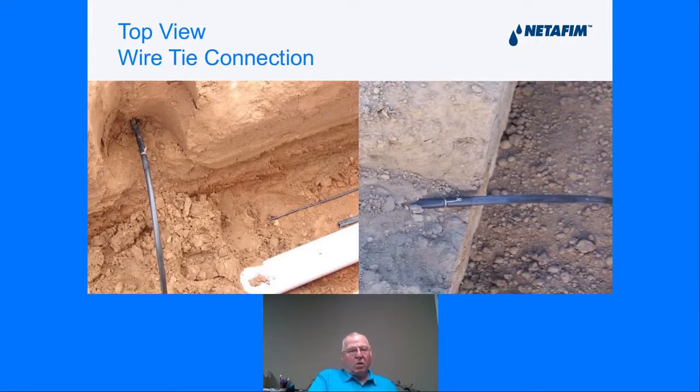these pictures here are a picture of a good riser slipped inside. It slipped past that, not the emitter, the dripper line. That tube is slipped past the dirt line there, and it goes on into the soil 4 to 6 inches inside that dripper line, and that supports that connection.